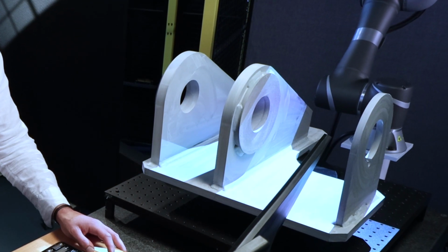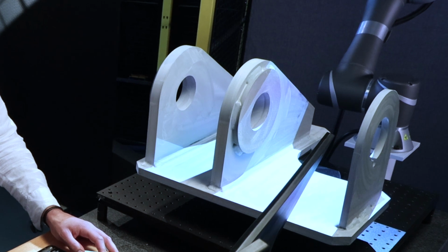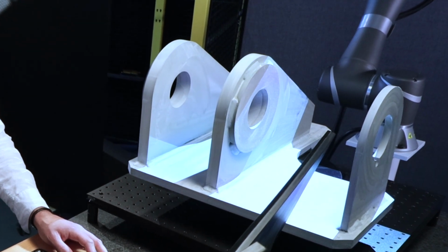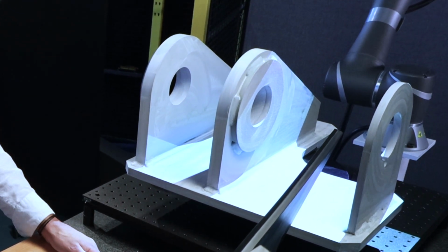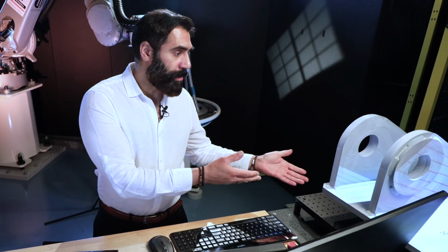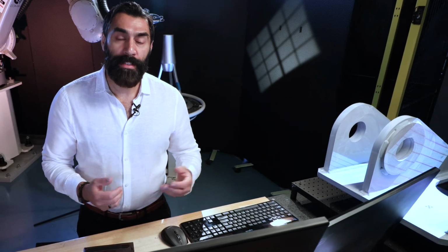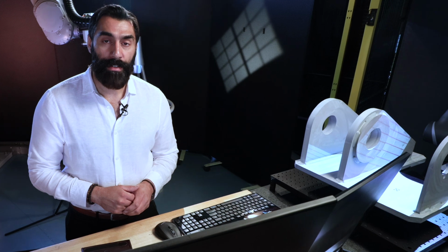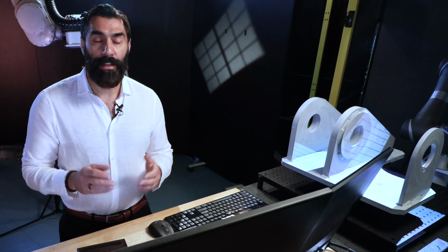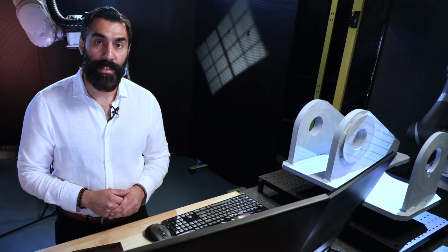The part has been welded at Fronius headquarters in Indiana and has now been shipped back to us here in East Hartford, Connecticut at CCAT. We have the part set up here on the rotary table, ready for the inspection process. We're going to show you how easy it is to set up that process in PolyWorks Inspector software to be able to measure the leg length and the length of the welds using model-based definition.